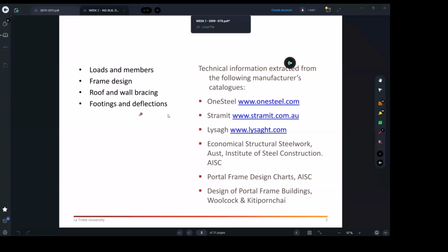Maybe I talked to you about those stories. The way you connect the members together may have been misunderstood, and that caused your beams to be loose. Remember last week we said there are rigid connections and pin connections. Maybe the engineer was talking about a rigid connection, the expensive fixed one, and it was built as a pin connection, and you ended up pinning it. That will make your members loose. So that means you need to know what we mean by deflections.